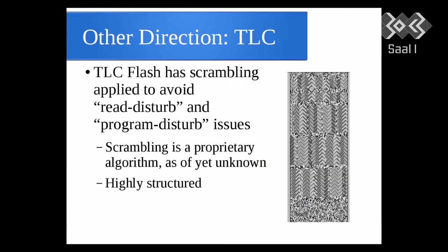In order to minimize this problem, they have to manipulate the data that's stored on the card by XORing it with a scrambling algorithm, which helps distribute the states across the data. It's data dependent. It's a proprietary algorithm. Every vendor has a different algorithm. But as you can see, the data is highly structured. I just took one of the raw dumps we have and put it into an image viewer, and you can see there's a lot of structure in the code. It's not for a security type thing. It's more just making sure that the statistical properties of the data stored are consistent with something that minimizes the read disturb issues.